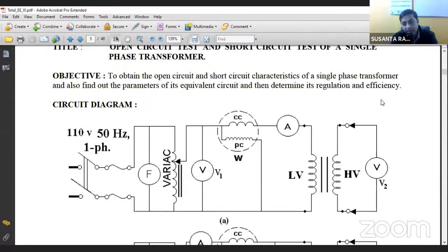That is the rated current, or sometimes it is also called the full load current. That value we can also get from the KVA rating and the voltage rating on the nameplate of the transformer. Now, at this condition, the current which flows through the primary is very low. It is almost 2 to 3%, as you have mentioned, compared to the rated current.